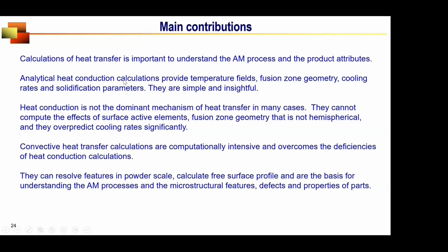And analytical heat conduction calculations are very elegant. They provide temperature fields, fusion zone geometry, cooling rates, and solidification parameters. They are simple and insightful and should be used where possible, where the fusion zone size is small, where the Peclet number is low, this is an excellent choice.